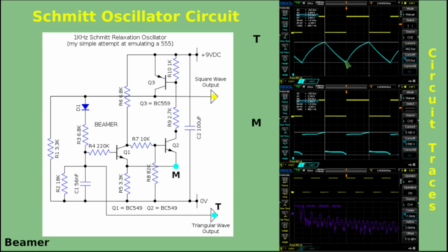Moving down to this trace here, which is a blue T, so we're looking at the blue T spot, which is that point there, and that is of course measuring the voltage across the timing capacitor. So this is the timing curve that's in sync with, naturally, the output. And the base of this signal here is at 3.56 volts, and at its peak it is 5.9 volts. So we're looking at a difference of about 2.4 volts.